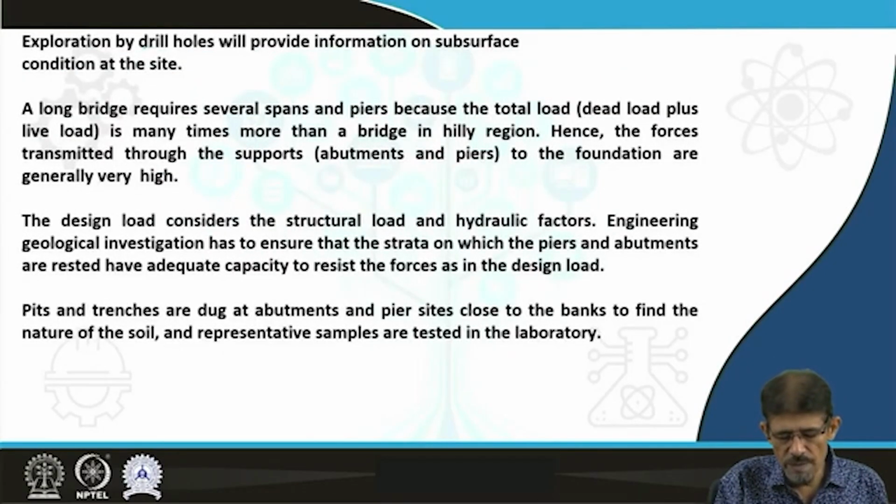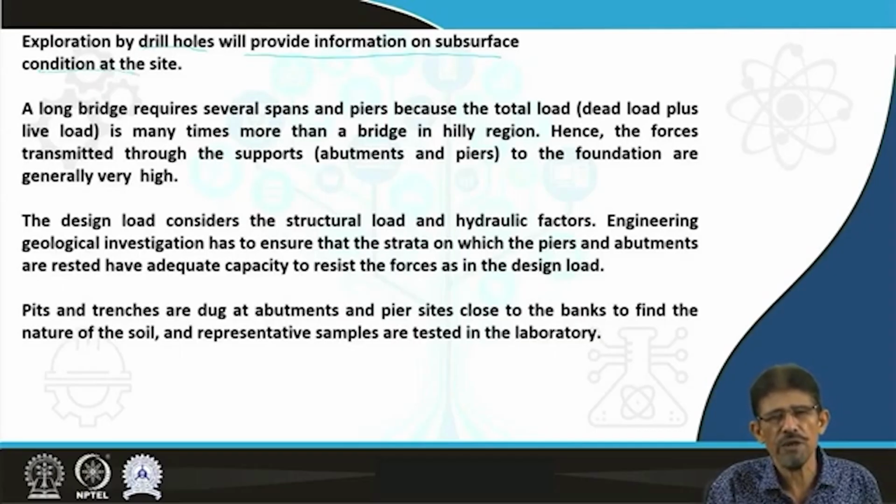The exploration of drill holes will provide information on subsurface conditions. For this, we have two types of drilling system, rotary and percussive. Through both, we collect samples through samplers and establish a suitable log, either belonging to rock lithologs or soil lithologs. In this way, we see the actual situation of the subsurface strata lying below the proposed bridge foundation or pier sites.